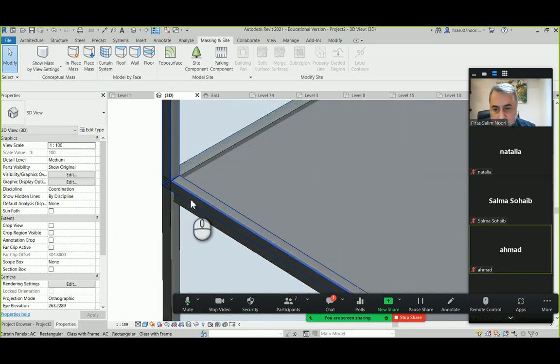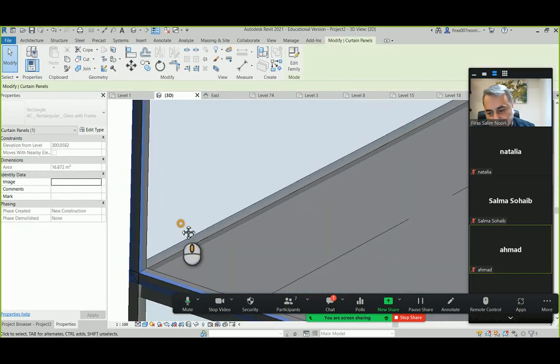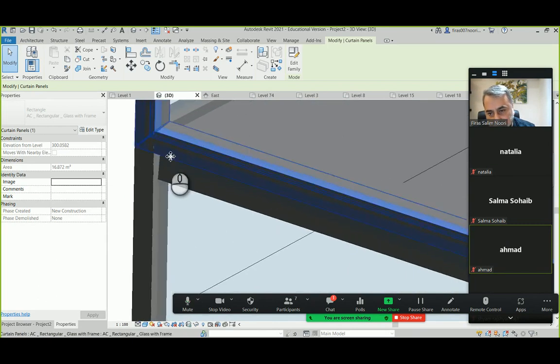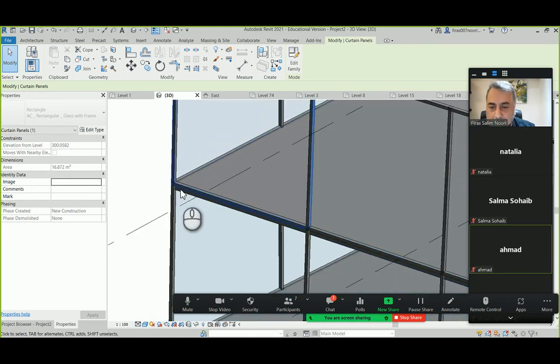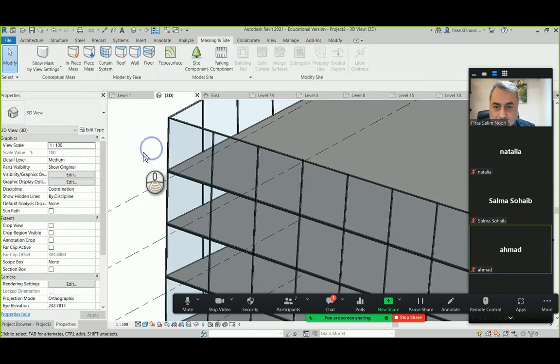It's a bit of the slab lower than the panel. That's okay. You can shift the panel down or offset the slab above because that's on the center. That's from the center and going down by the thickness of the slab. If you see this detail, don't panic. The real reason is that this one is 80 mm wide and this one is 150. Remember the point. So you have to fix the width or the center for that. Draw it and you understand what I mean. But other than that, it's perfectly correct.